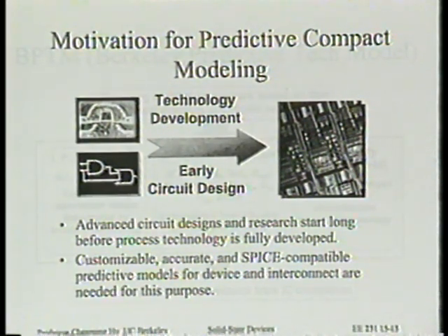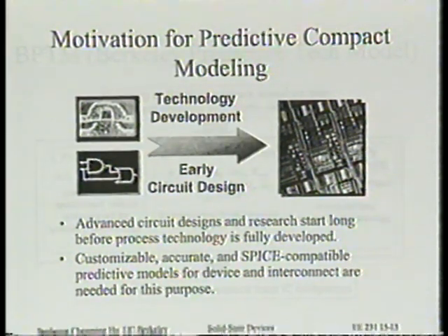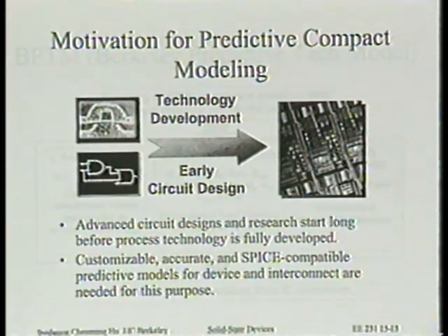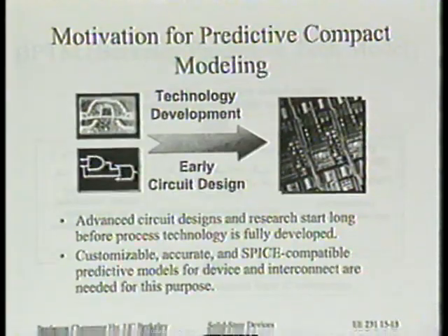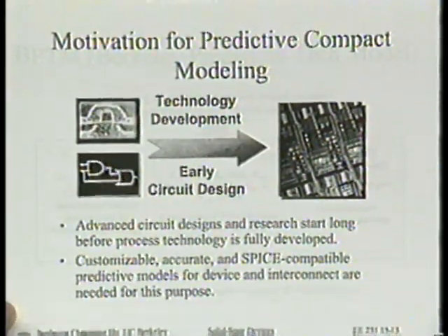And can that user further, just on his own, with one keystroke, say, gee, I want to reduce VT by 0.1 volt, and then see how my circuit works, rather than waiting for TSMC to provide some data for this, and still have some confidence the model is accurate, right? What if I have a technology whose oxide is thinner by 10 angstrom or something? And so this is called predictive compact modeling, all right?